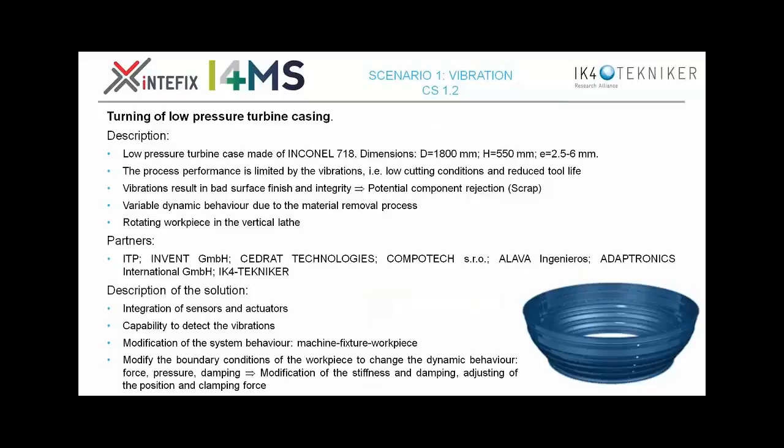So here the idea is to be able to change the boundary conditions of the component in order to modify the dynamic behavior and dynamic stiffness. If we change the dynamic stiffness, we change the behavior of the workpiece and its response to the cutting forces. So here the idea is to integrate sensors to monitor the process, and also to integrate actuators.